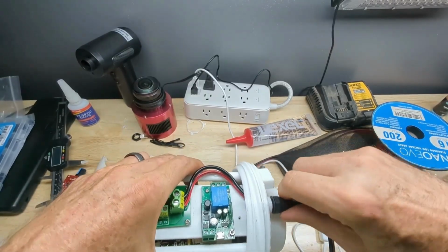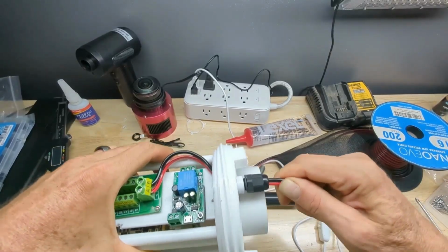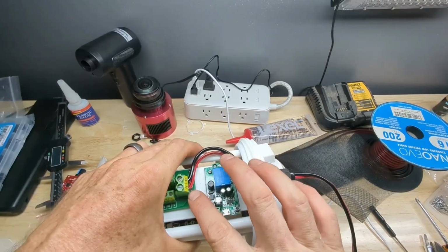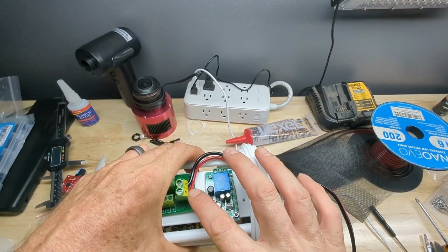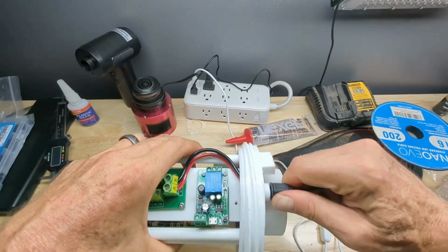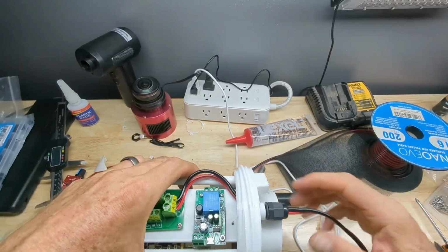you'll be very hard pressed. You will definitely have to really be trying to get this to actually pull out and potentially separate from up in here. And I do have a little gap on that cable. I need to get that pushed up in there just a little bit tighter, but you definitely want to make sure this cable gland is tightened so there's absolutely no way this cable can accidentally get tugged and yanked out.